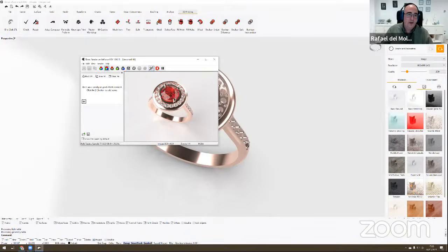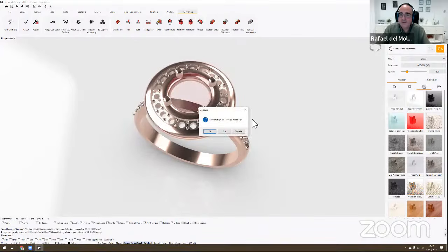That's all of this exercise. Okay, now it's 100, but I think you understand. And the result is really cool. 100, the result is really nice. Okay, let me close. And that's the exercise. We import the design, we modify the stone, the finger size, we generate a technical report, we create a gems map, we create the report, we export the STL, and we do the render.